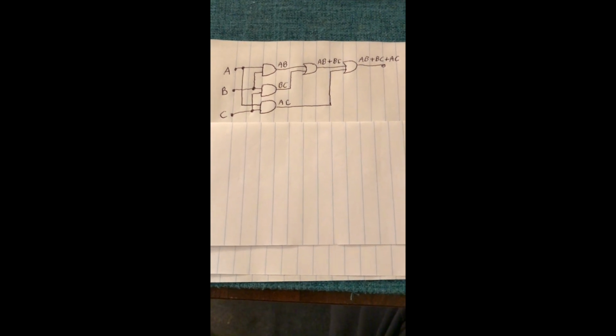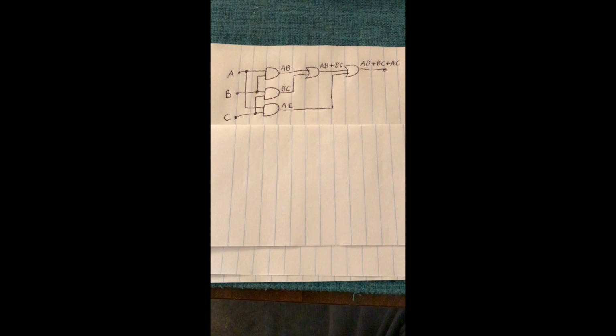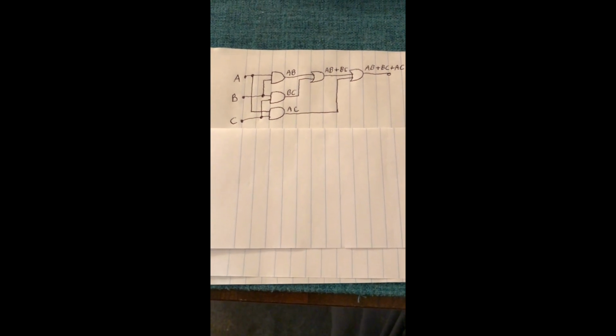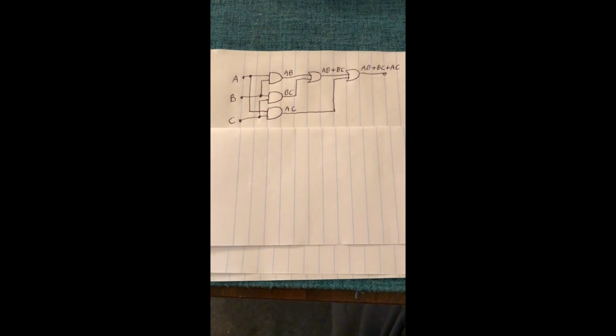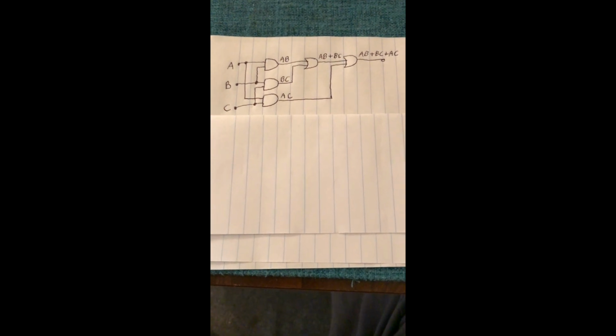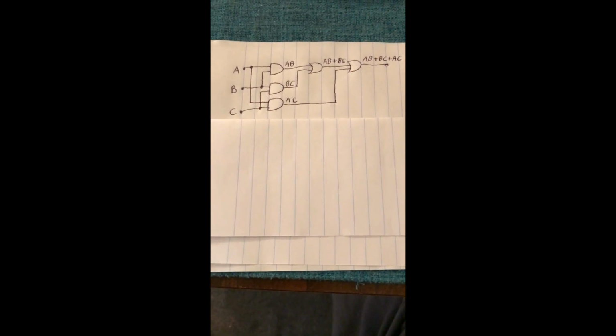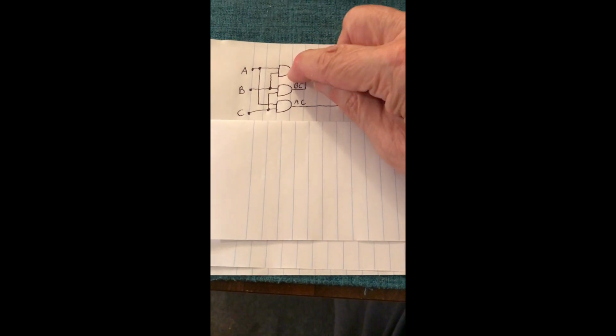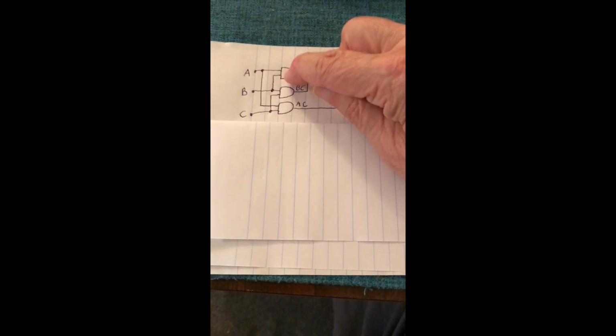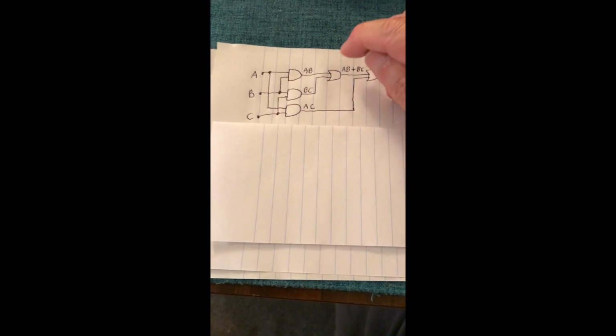So then the question arises, how do we combine AND and OR gates to make a circuit that can detect a majority of inputs being turned on? Then to turn on an LED, for example, or a little audio oscillator or something, something to process the output. This is a symbol for an AND gate, which in our case is 2 transistors connected in series. And this is a symbol for an OR gate, which would be 2 transistors connected in parallel.